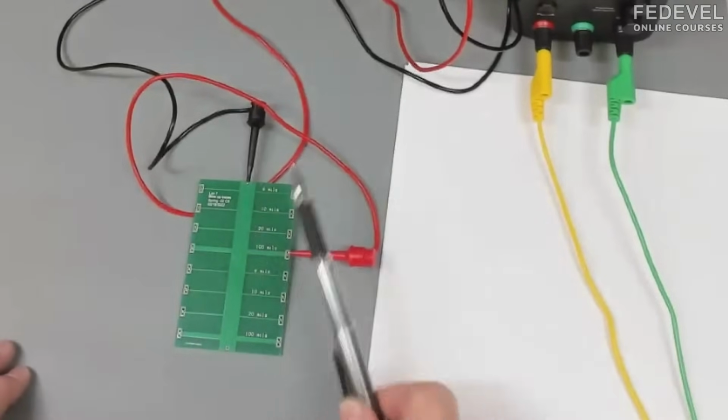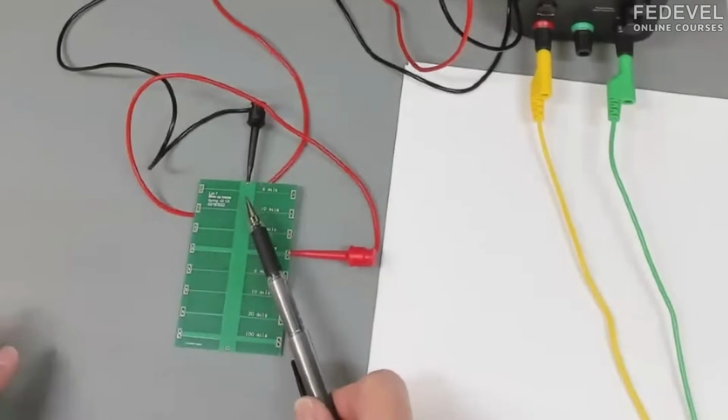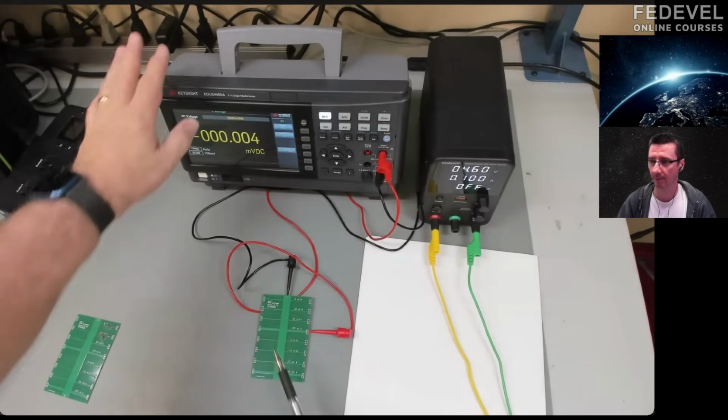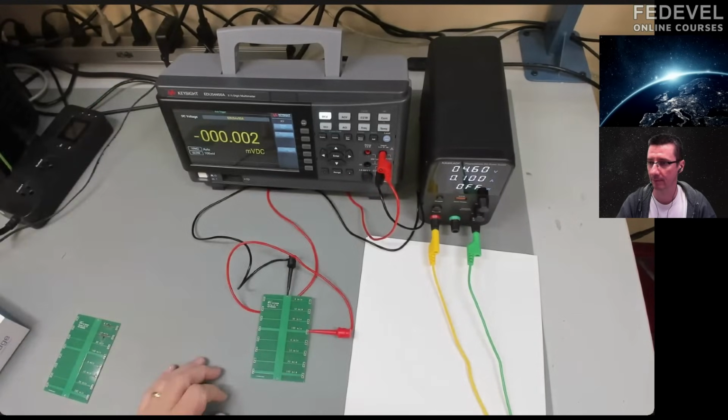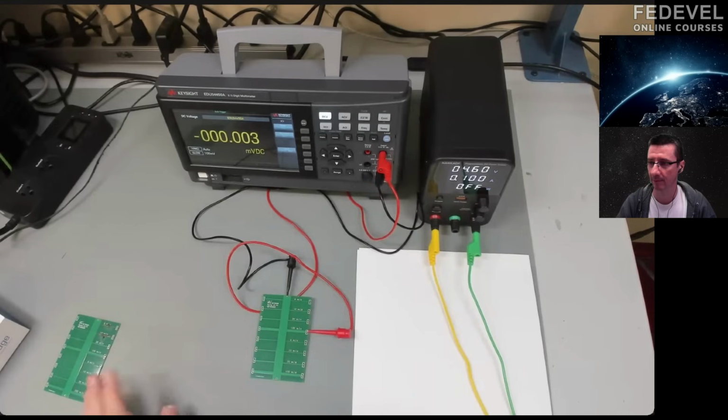They're set up in a specific way in order to use a standard digital multimeter as an ohm meter to measure the resistance. They're also set up to use the special technique I'm introducing, the 4-wire method, and why it's so important. And we can measure the resistance, and we can also crank up the current through them and look to see what happens to the trace.